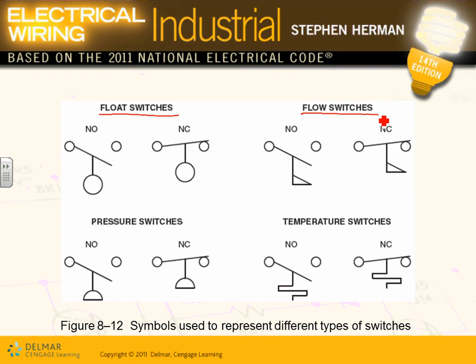Do you guys remember the tamper switches and flow switches that we did for the fire alarm system? Exactly like this. If the water comes here and hits this mechanical part, it pushes it to close, and now you have 120 volts here that's going to energize something coming from here, and here's a motor. Now my motor starts.